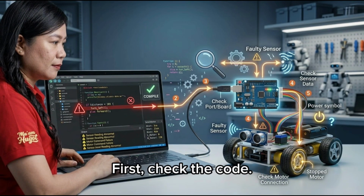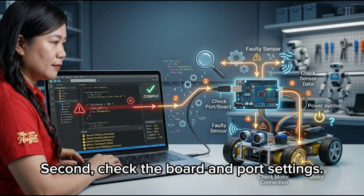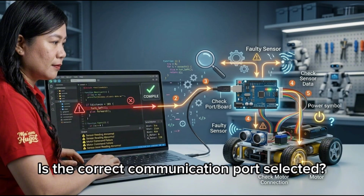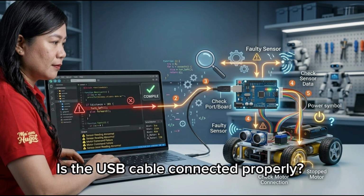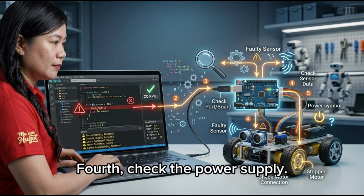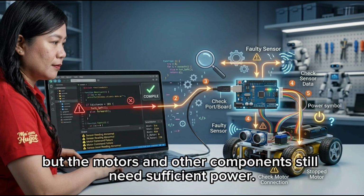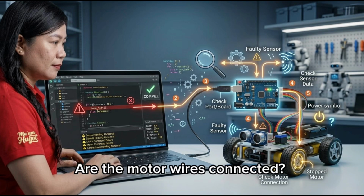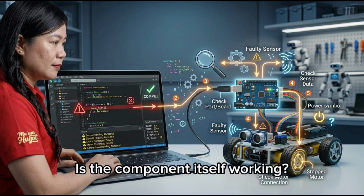First, check the code. Does the program contain syntax or compilation errors? Second, check the board and port settings. Are we programming the correct board? Is the correct communication port selected? Third, check the connection. Is the USB cable connected properly? Is the controller communicating with the computer? Fourth, check the power supply. The program may be correct, but the motors and other components still need sufficient power. Fifth, check the hardware. Are the motor wires connected? Is the sensor connected to the correct pin? Is the component itself working?